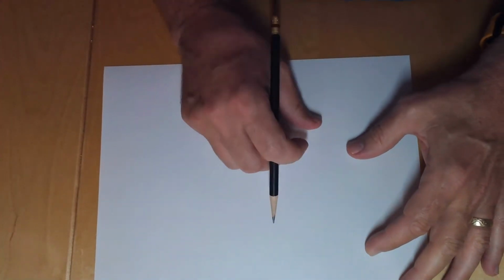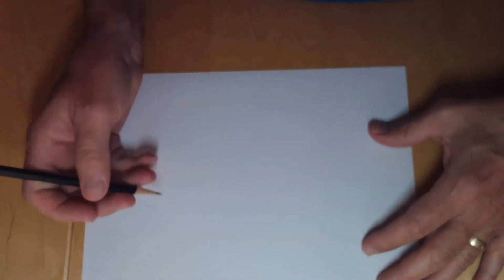Sketching, the line quality is going to be very important. Also, the technique that you use for sketching is going to be very important. And we want to use the natural geometry of your body to help us to create straight lines. When I talk about line quality, there's basically two types of line weights that we're going to be using in class in our technical sketching. There is thick, and then there is thin. We could throw in a third one, which is going to be very important, and that is construction weight.